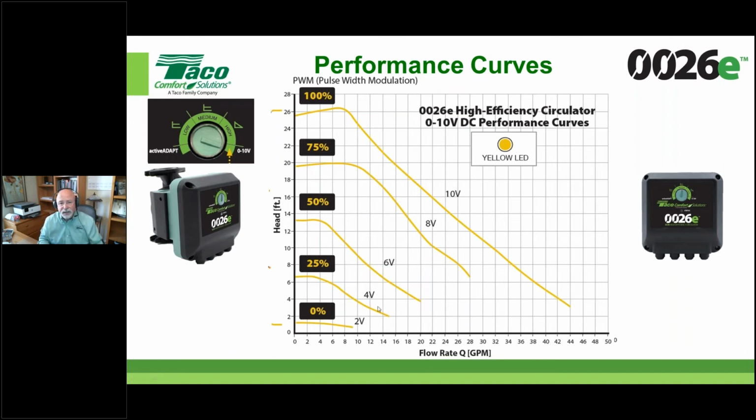And it just looks at, typically starts at around 2 volts, and you've got a linear up and down RPM selection up to 10. 10 is max speed, and around 2 or 1.5 in some cases is the low speed. So again, we're handing the keys over to somebody else at this point in time.